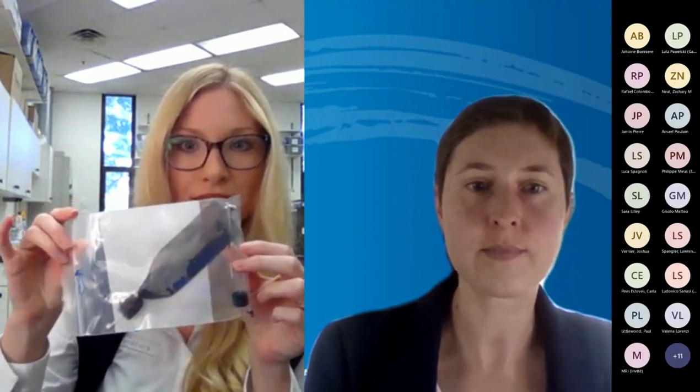And how do you recover the dye afterwards? What technology do you use? Oh, thank you for asking. So we use both water sampling and charcoal sampling, which I think is a little different from what some other folks may use. We really like the charcoal sampling. I can show you an example of what that looks like. We just have little mesh bags filled with activated coconut charcoal. These are passive receptors. We deploy them in the water. We use those to collect initial background, and then we also use them in our post-injection sampling.